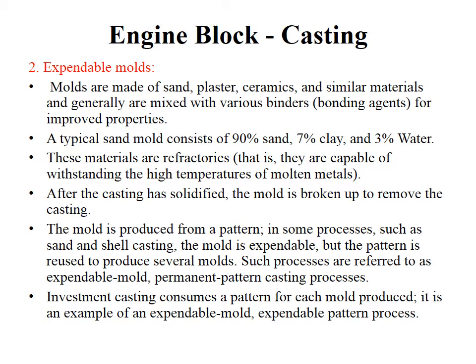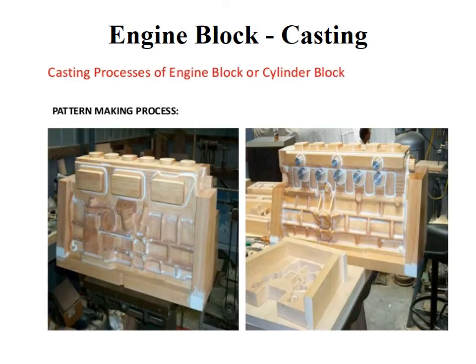So in this, the mold will also be destroyed once the casting is done, and also the pattern will be destroyed. So here you can see the pattern making process, which is nothing but the casting process of an engine block. So you can see that the pattern is made up of an expendable material, which is nothing but lost foam, which we'll be discussing in the next slide.